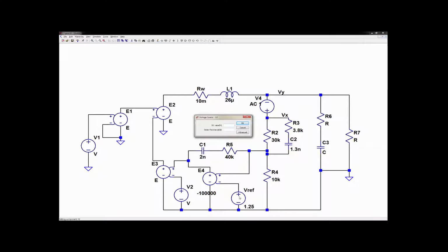Now, since this is 1.25, and we know what our duty cycle is going to be roughly, it's going to be 0.227 to create the input voltage of 22 volts. 22 times 0.227 is going to be 5. So we need an offset to push this up, so that when we put a real op amp in, it will push up this output, which should be reflecting a quarter of this. So therefore the reference is 0.5. We're going to push up the reference here so that this now will be 0.5.